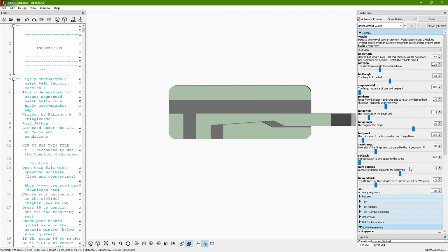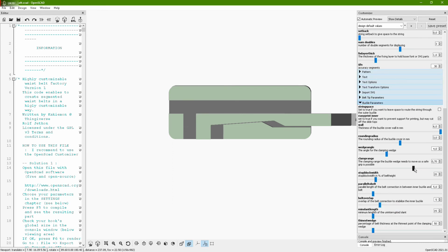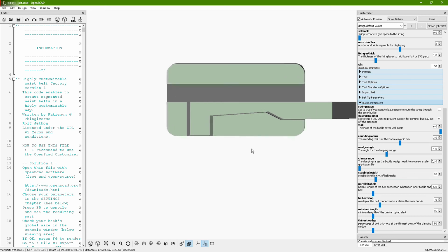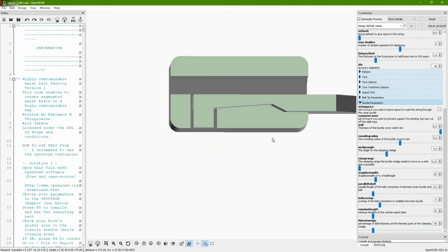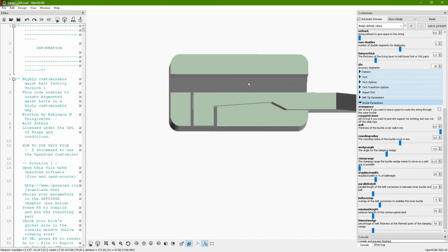And that's defined here. We say, okay, at the moment it's 0.7 millimeters, right? So I can go to 0.1 millimeters only. Therefore my buckle will become much shorter, right? Yeah, but I don't have to move that much here. But with 0.1 millimeter, your prints would have to be very, very exact to still squeeze it. So I think you should have at least 0.5 millimeters to still squeeze it.